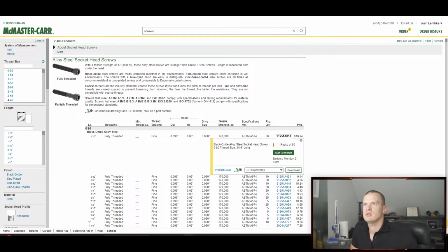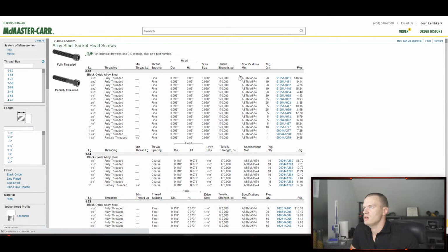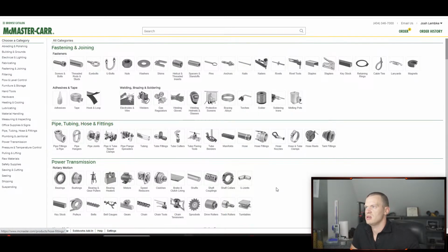Now, as Hyperactive Snail mentioned, the CAD for everything is not perfect. And on really critical things, like if you're doing screw threads, if you're doing gears or something like that, it is very important to check and make sure that if you need that geometry to be perfect, that you double check it yourself. So like I said, this is McMaster-Carr, and as Hyperactive Snail has said, the models for gears on McMaster-Carr are not necessarily perfect all the time, and sometimes they can be quite a bit off.